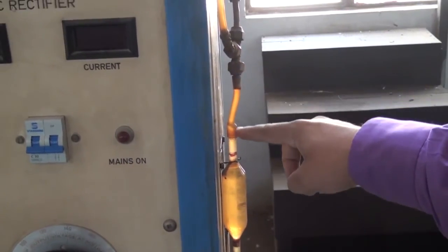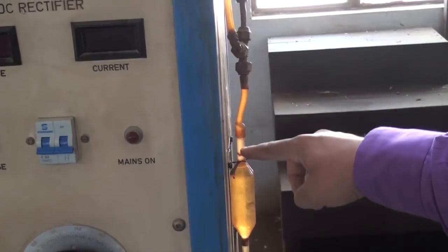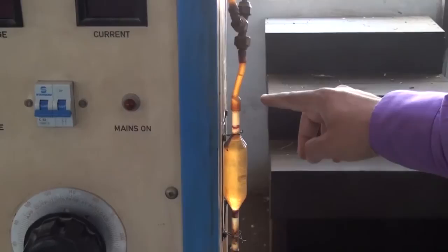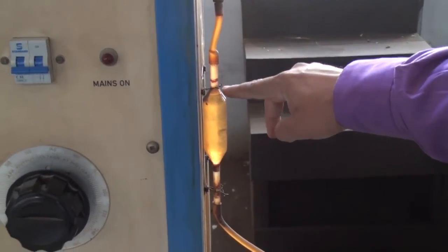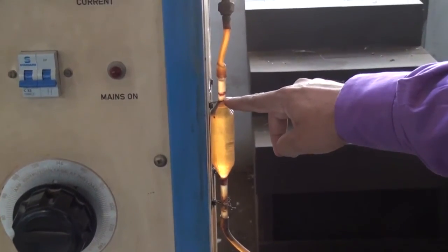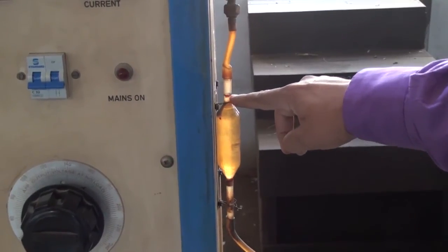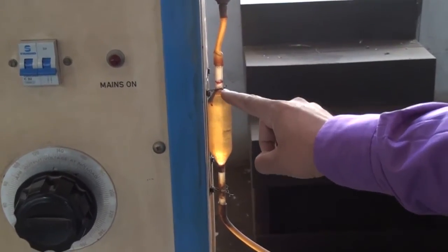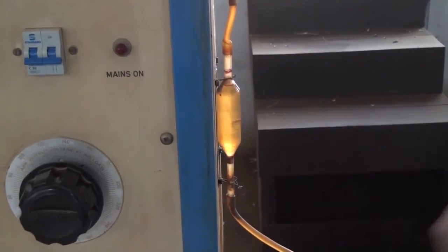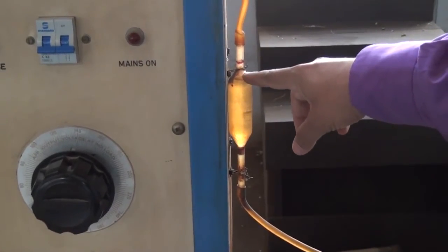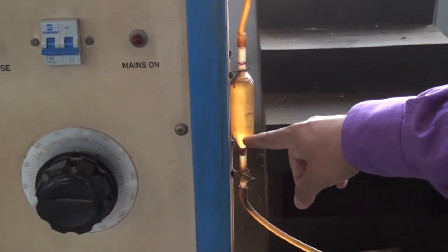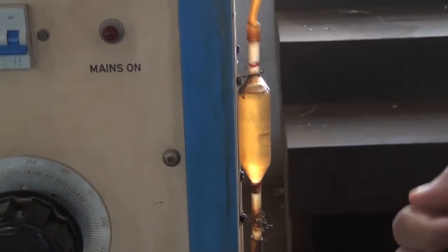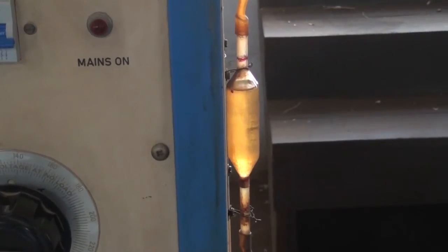So we'll move it down and we'll see this. It is still not come. Yeah, now it has come. Once it is there, now we'll start the reading on a stopwatch. Now the fuel is being consumed. We'll see the amount of fuel consumed in a fixed time. Once this fuel is consumed, it will reach this level, you stop the stopwatch and then that time will be noted.